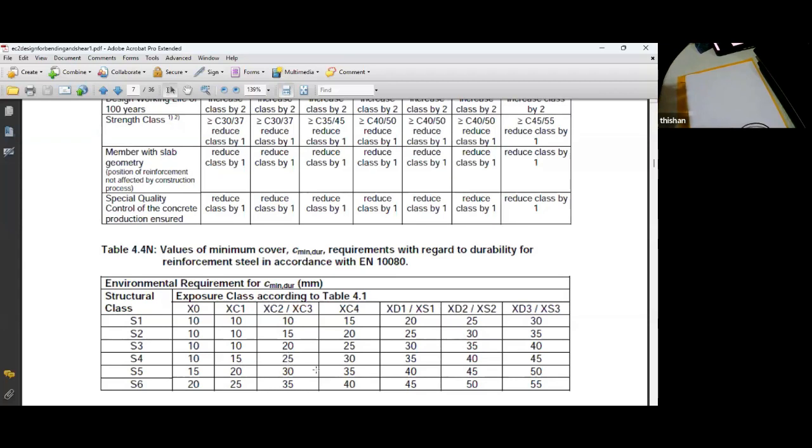They say keep a tolerance. And for bridges, you can see the cover is about 5 millimeter more. So the cover in bridges should be 40 millimeter, whereas in buildings it can be 35 millimeter, but can be reduced to 25 in slabs, provided that you are careful. So it's not a major deviation, only about 5 millimeter extra in the Eurocode than what you have used in the British code. So it's not a major thing, but you have to keep in mind the cover is 35 millimeters.